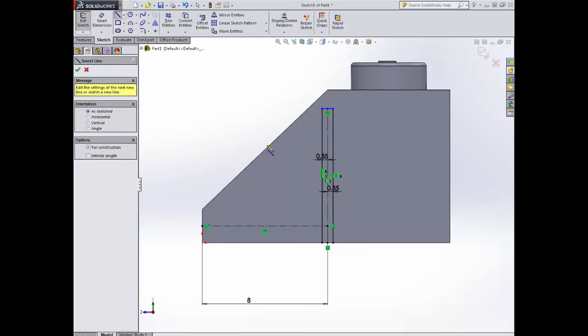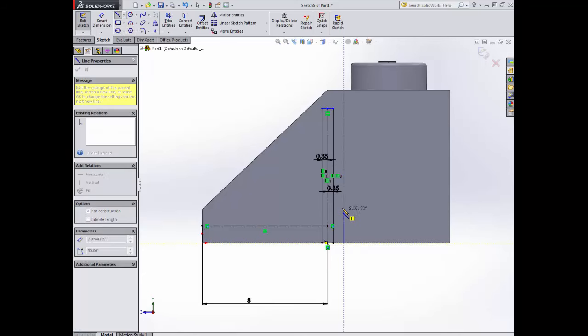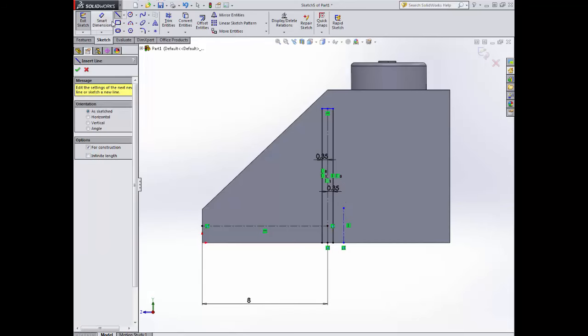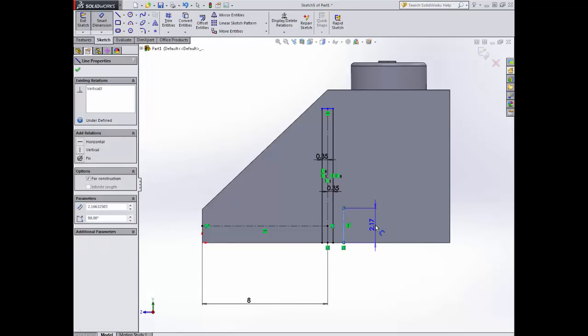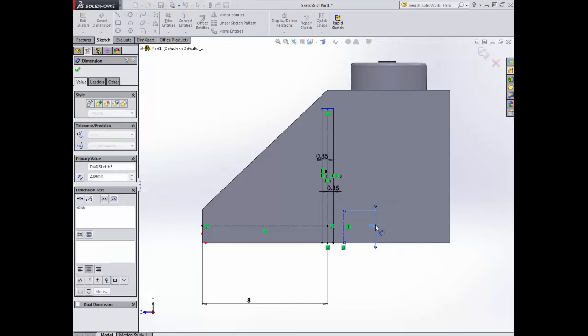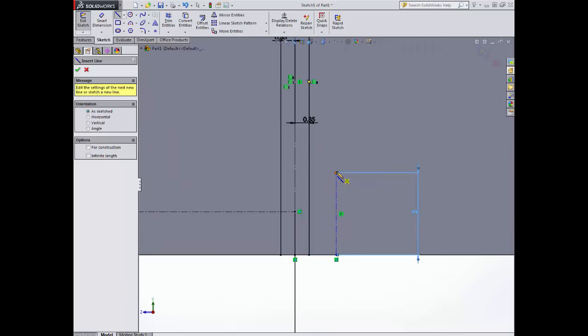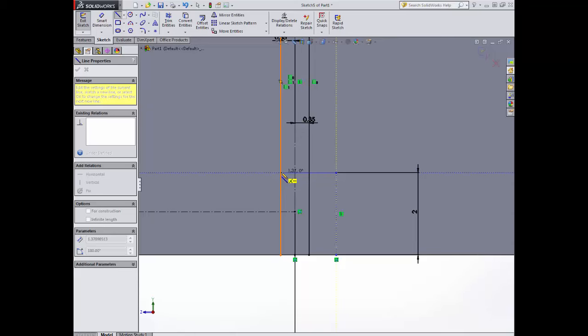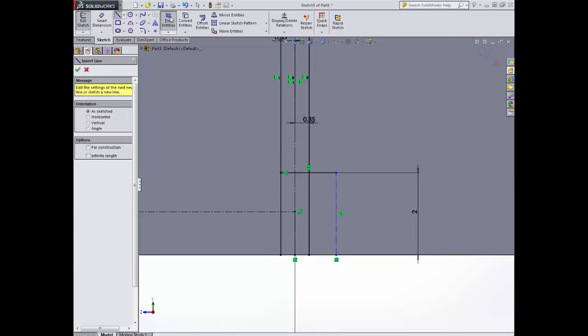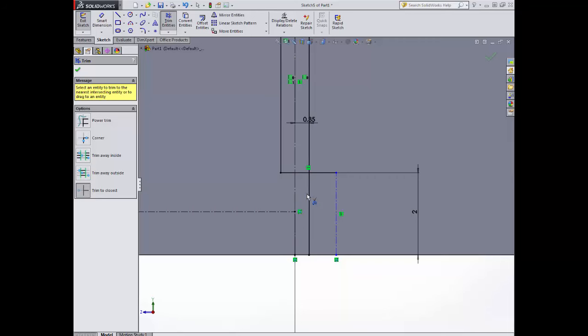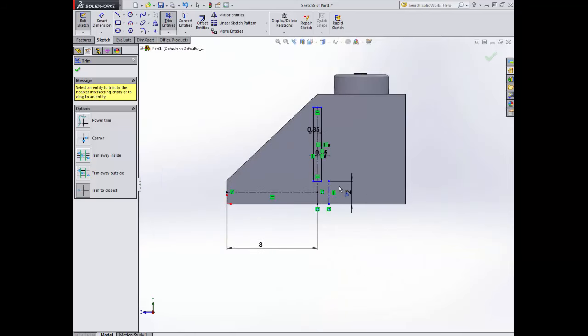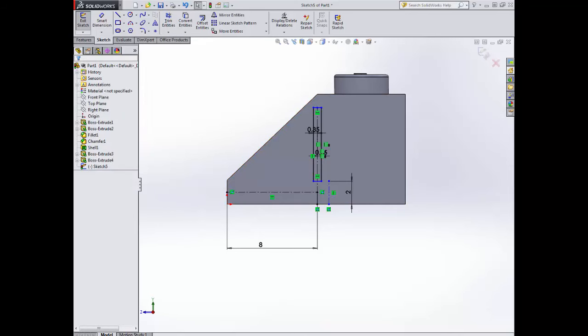Okay, as you'll notice from the technical drawing, there's actually a gap where this web actually sits. So I'm going to start off by making sure that's the right height. It's 2, so 2 in there. And as I said, I'm now going to make sure this is closed off. Now I could try and draw across here. The easiest way though is to zoom in. I've got some trimming to do anyway, so click on that line, double click, and up to my trim tools. Trim to close is ideal here, and then just snip away the lines. Obviously the centre lines will also stop the trim tool, so you have to be quite careful with that. And now I've got my island floating in space.